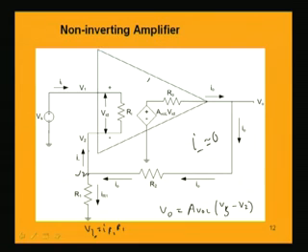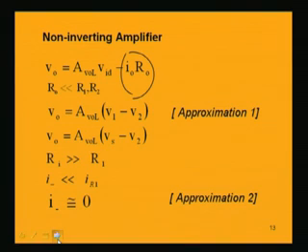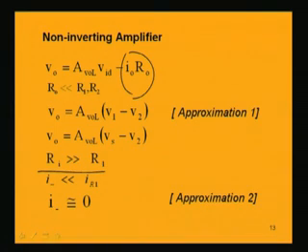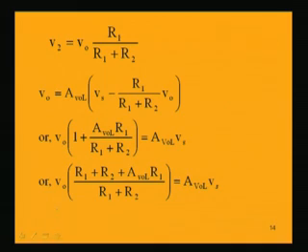That approximation we will be using, and then our task is easy, because if we want to find out this voltage, the voltage division is taking place, the same current flows. So, V0 into R1 by R1 plus R2 becomes V2. Here we are using that approximation, and that approximation is exactly valid, because Ri has a very high value, it is in the order of megohms compared with R1 or R2. So, then I negative is very less than IR1 and we make it equal to 0, and then we get V2 equal to V0 into R1 by R1 plus R2.